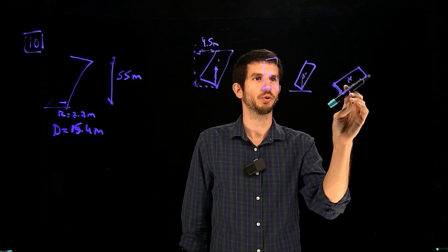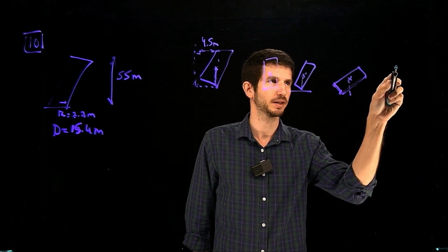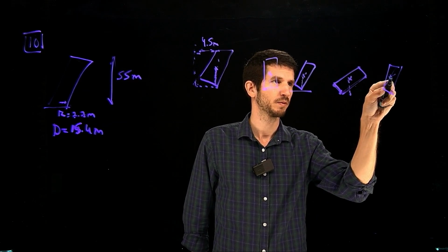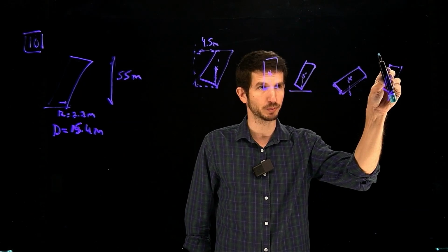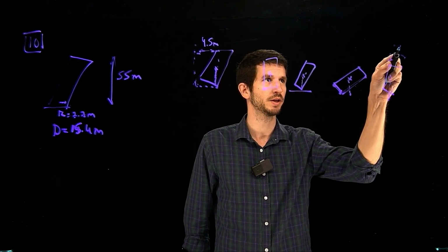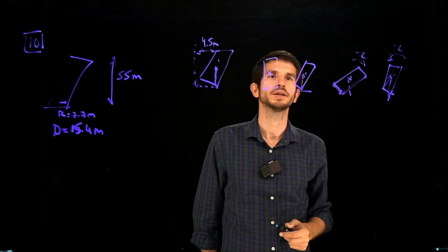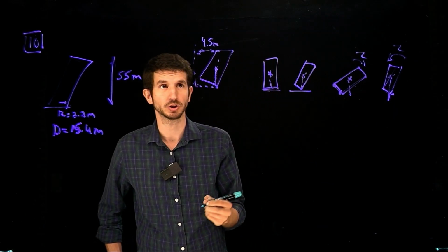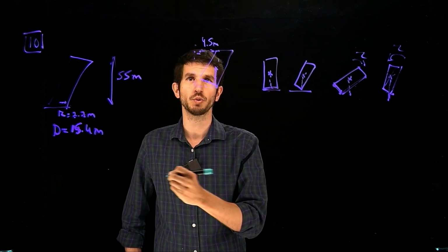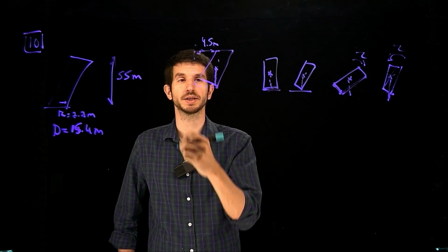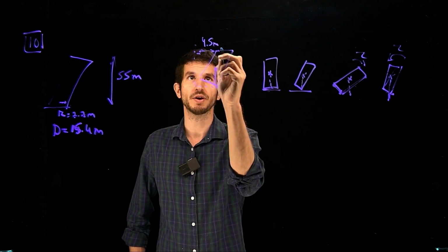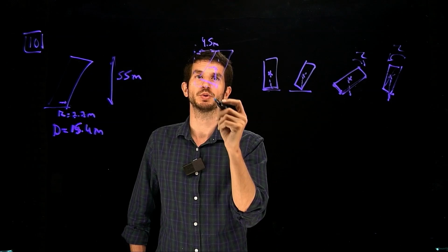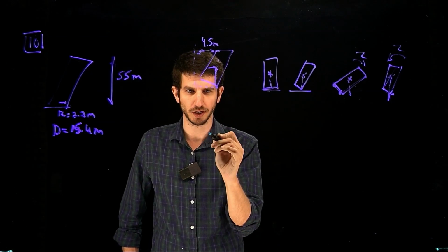If I let the object fall when it's, let's say, slightly tilted, where this is obviously within the base, it's going to drop that way, right? So the torque is going to go this way. The torque in this case is going to go that way, right? So that's what we're discussing, as we just said before. Okay, so the question is, is it in equilibrium or not? To see that, we have to see where the center of mass falls with respect to the base. And of course, because it's 4.5 meters, let's make the diagram.